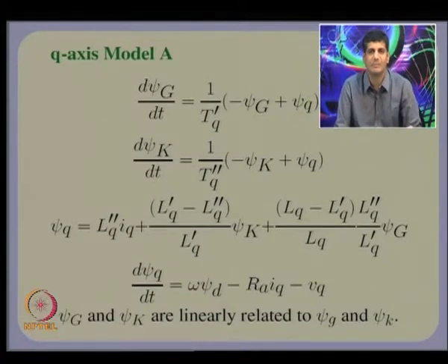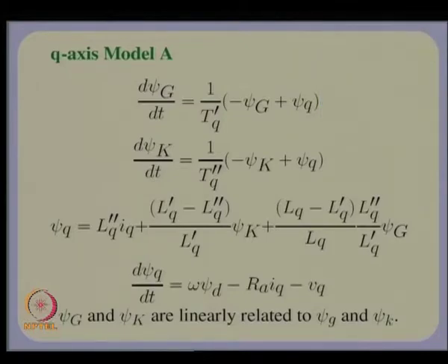Just remember that. But nonetheless, in most studies we do not require to know exactly these fluxes. You only need to know what effect these fluxes have on the stator side. In that sense, this is a valid model because it gives you the correct transfer function relationship between the observables on the stator side, that is psi q and iq. So, that is the important point.